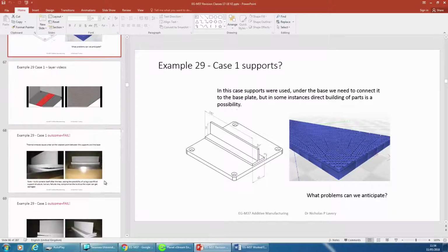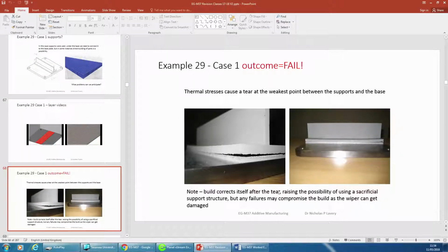So just to show you some of the failure, when you locate it flat on the plate, this is an in-process tear that has happened, or delamination or tearing that happened during the process. You can see this classical banana shape where the part has tried to expand outwards like that, and it's taken away from the support structures, and it's ended up ripping itself apart during the process.